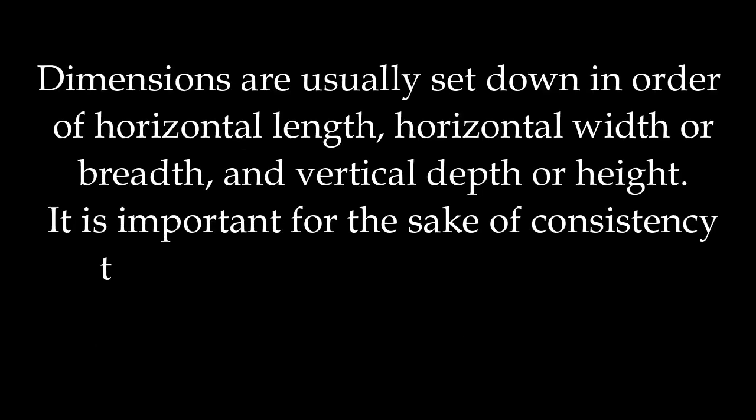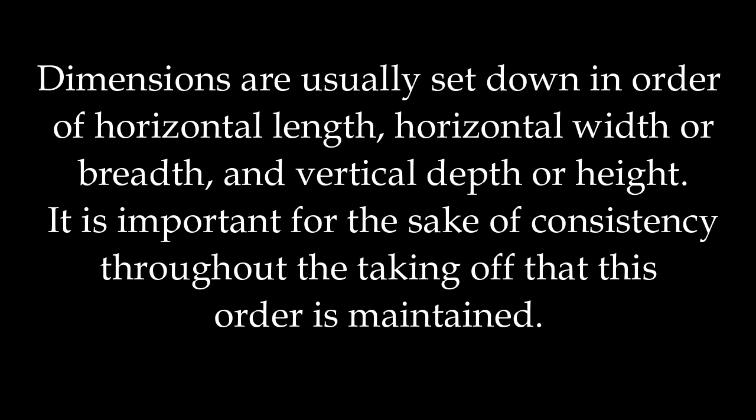Dimensions are usually set down in order of horizontal length, horizontal width or breadth, and vertical depth or height. It is important for the sake of consistency throughout the taking off that this order is maintained.